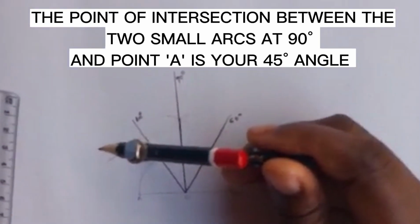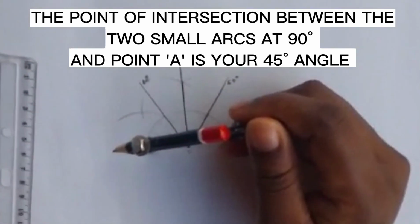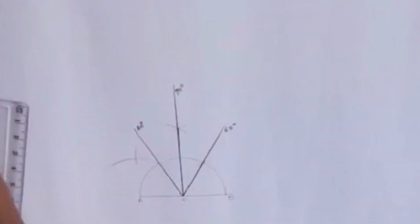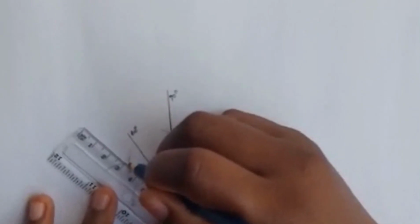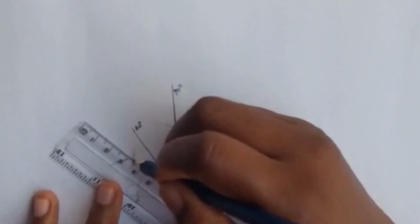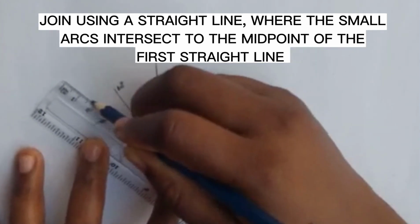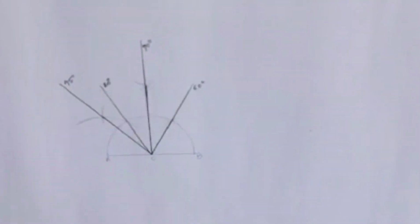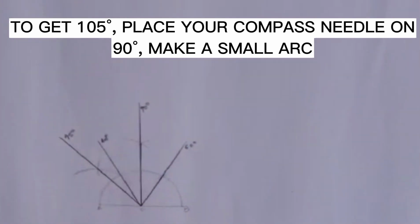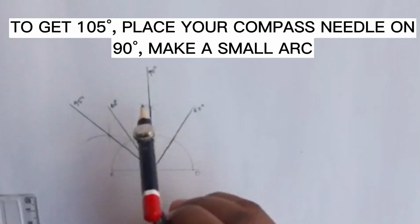So the point of intersection between the both arcs of 90 degrees and A is where you get your 45 degrees angle. So you put your pencil directly at the dots where the two arcs meet, and then you join a line right to the midpoint of the line that you created, and right here is 45 degrees.